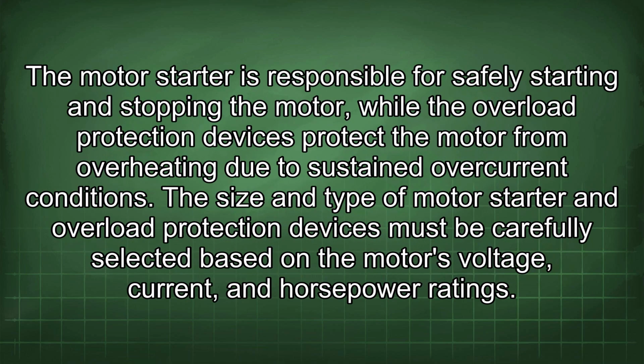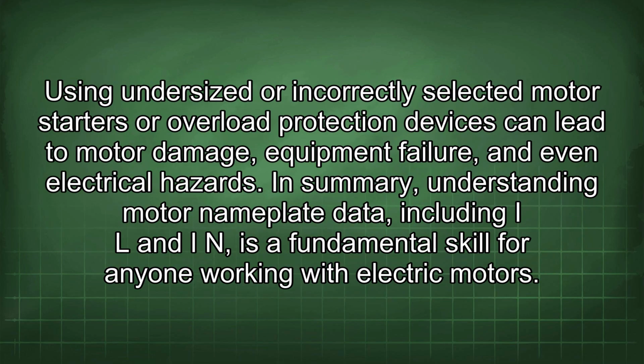The motor starter is responsible for safely starting and stopping the motor, while the overload protection devices protect the motor from overheating due to sustained overcurrent conditions. The size and type of motor starter and overload protection devices must be carefully selected based on the motor's voltage, current, and horsepower ratings. Using undersized or incorrectly selected motor starters or overload protection devices can lead to motor damage, equipment failure, and even electrical hazards.